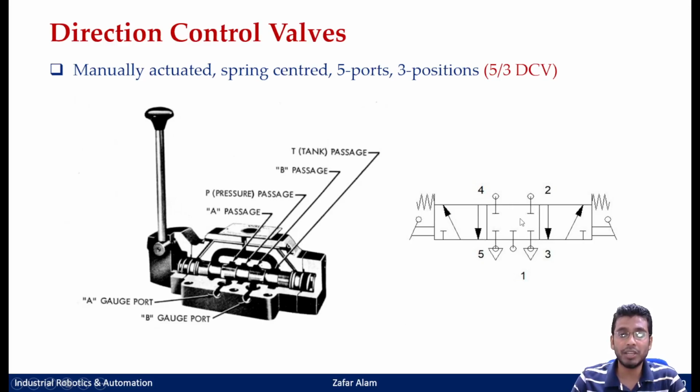Okay, now if I have to engage it, I may engage it using these positions. I may also engage it to the other side. But how would the default position be maintained? The default position would only be maintained by the spring that is there on both sides. So that means both sides the spring would be there. Now when I just pull the lever, one position would get engaged, and if I push the lever, my other position would get engaged.